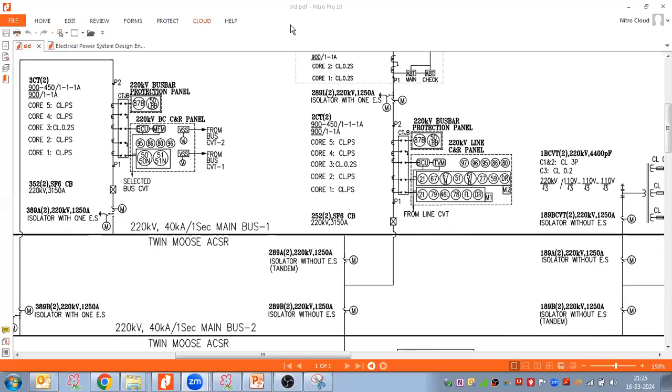The CT is required to cover certain zone of protection. So that zone of protection is quite important. So that coverage decides the position. Please come with interview point of view. You are in the interview, I'm asking you why you are putting it here. So do not tell the incomplete answer, tell the complete answer. Certain zone of protections, which you can tell all the protection zones, Suresh: we have line protection zone, transformer protection zone, and bus bar protection zone, right? If you tell like that, that would be a more comprehensive reply. Anyway, thanks, Suresh.